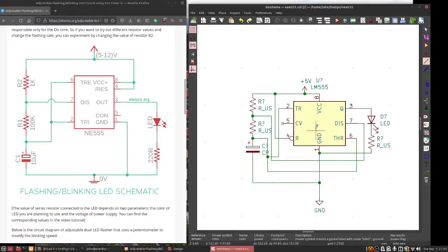It might be better to choose a different symbol in the schematic to stop having so many cross lines. The arrangement of the pins in the symbol really helps keep the schematic clean. But I think that's correct.